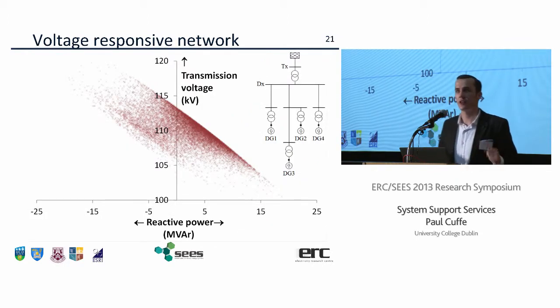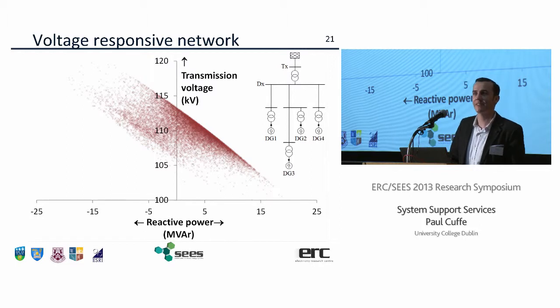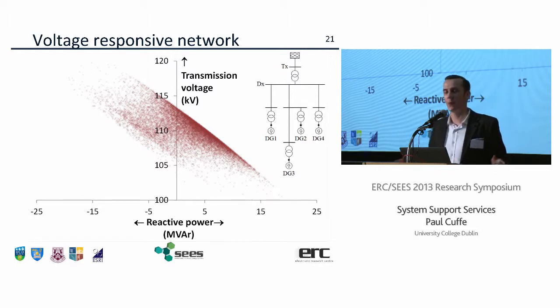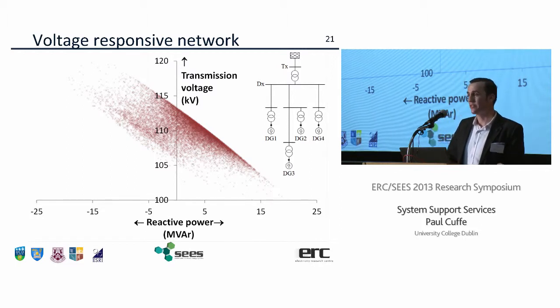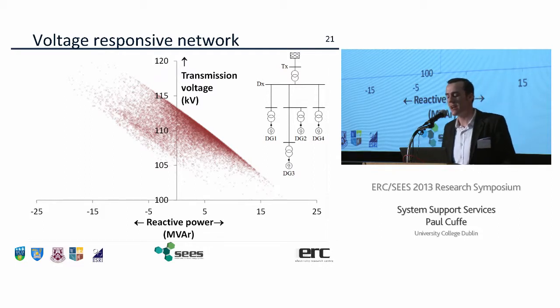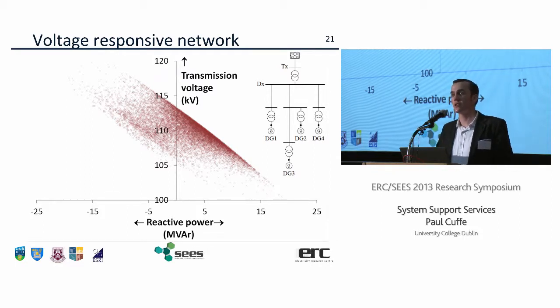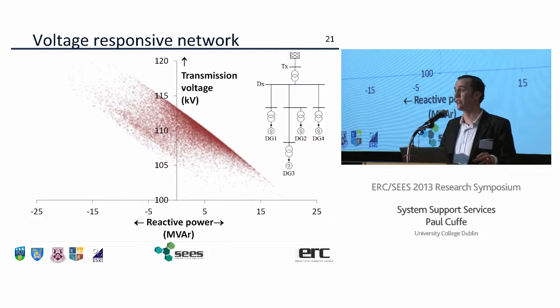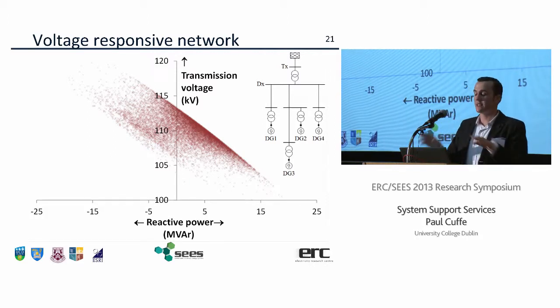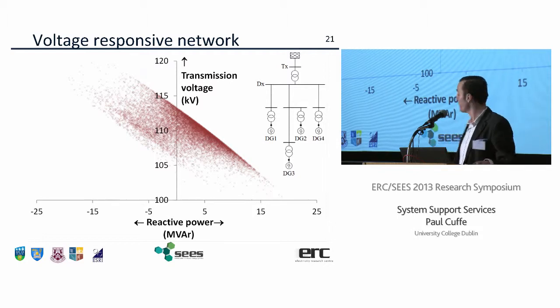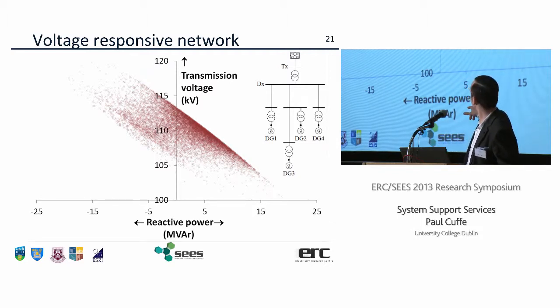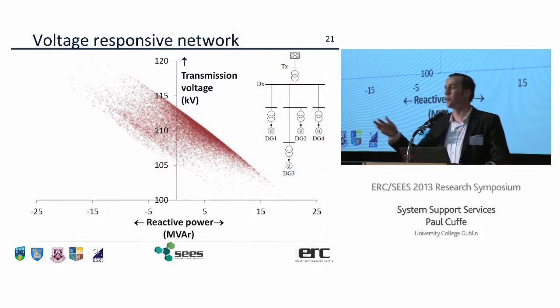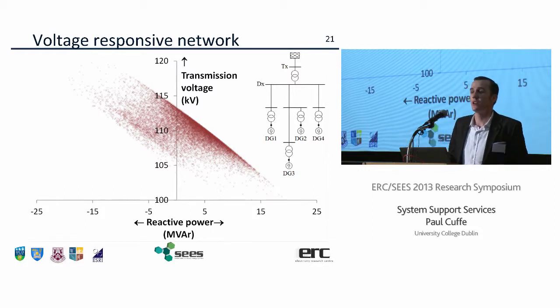It turns out to be tricky to implement, so we went back to that fantastic Swiss Army knife of AC optimal power flow. There's an example in this small network. We haven't quite got out to the big load networks because the problem becomes pretty big. But for these 4 generators and that transformer, in an optimal way, you can select their voltage control settings and that tap setting to get this aggregate response. As the voltage tends to go down at the transmission level, that summons up a reactive power injection, which is the sort of thing you'd want.